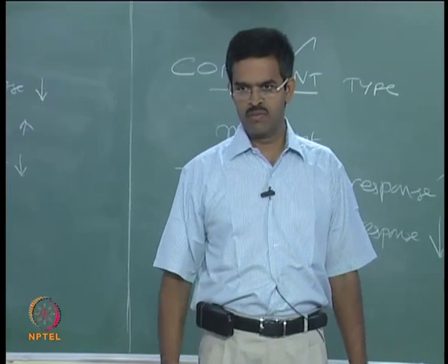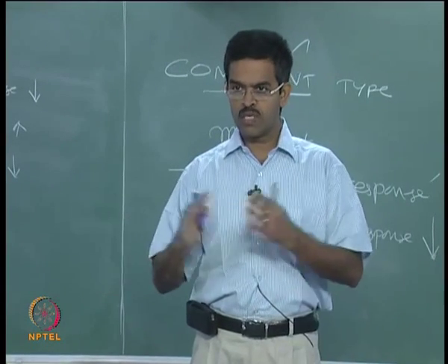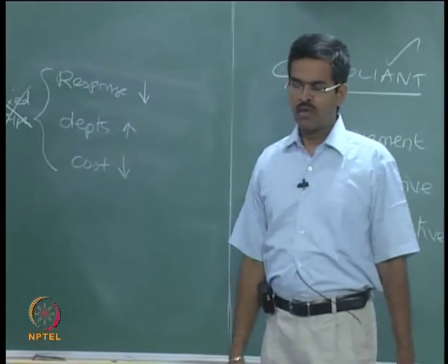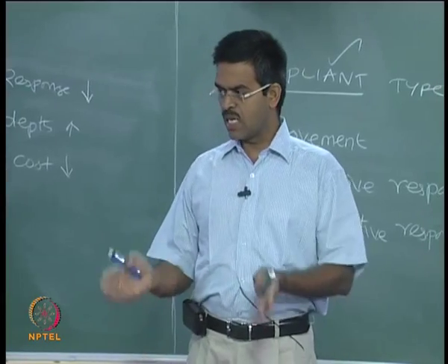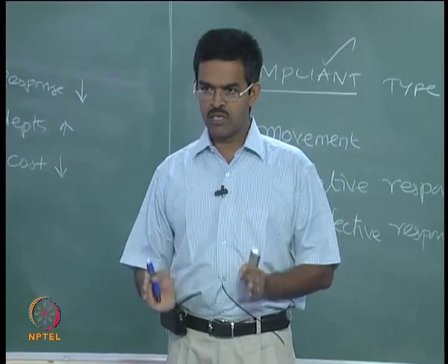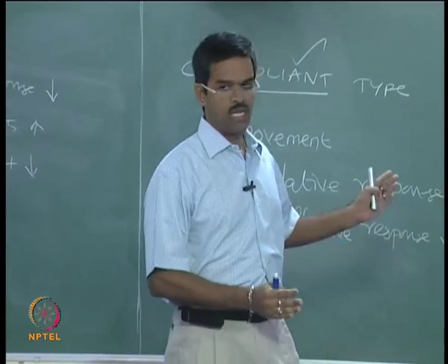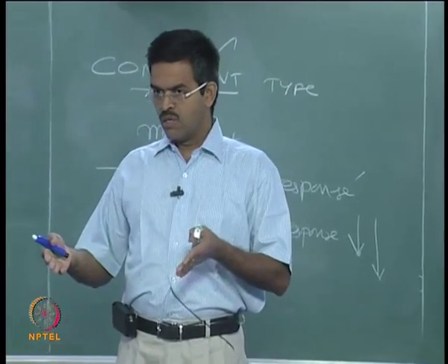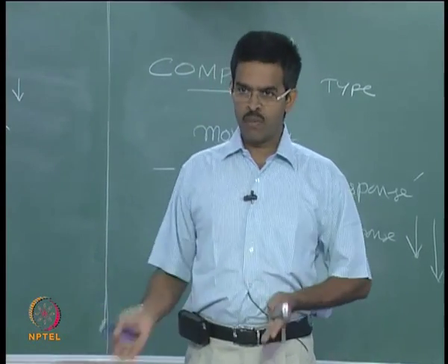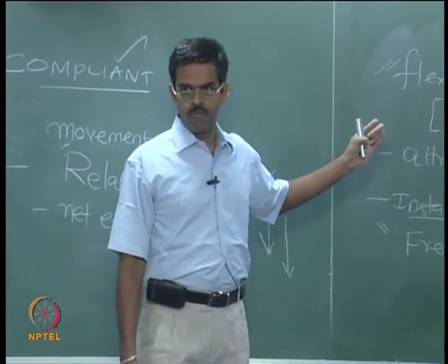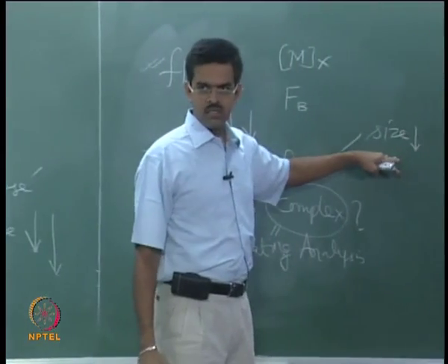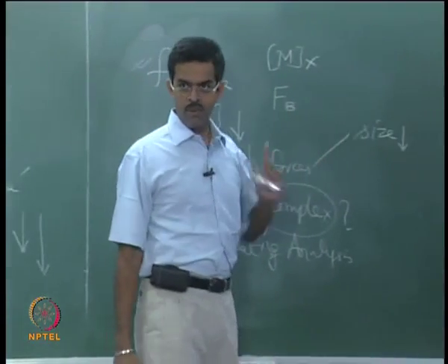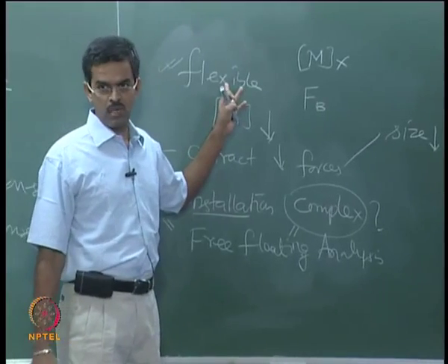because if you say I want all those top side complications to be installed which already exist in a fixed type for exploratory and production drilling, I must have all those equipments, plants, machineries the same as in a compliant type also, because any user will not compromise on the user oriented functionality of any platform because you want to make it flexible. So, the size more or less has got to remain the same. I am not saying it has got to be exactly the same, more or less it has got to remain the same, but the weight has to come down because it has to remain flexible.